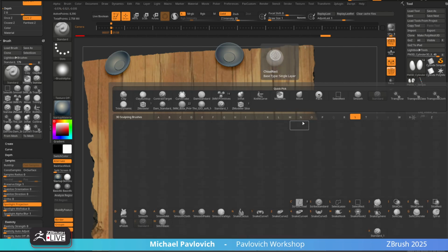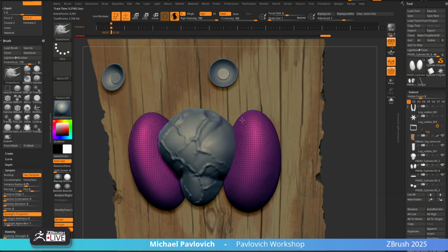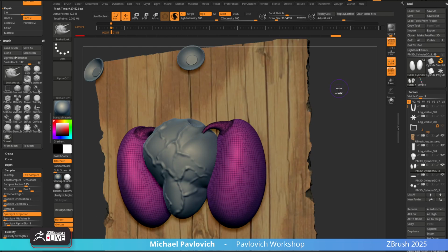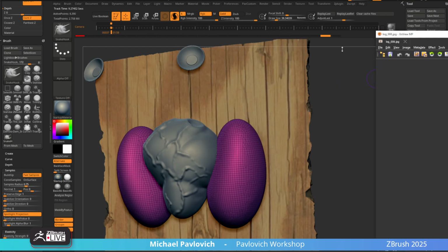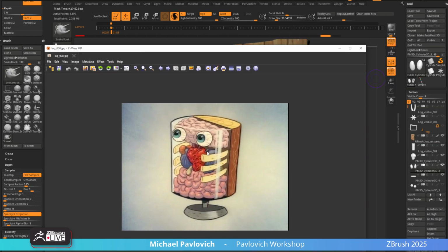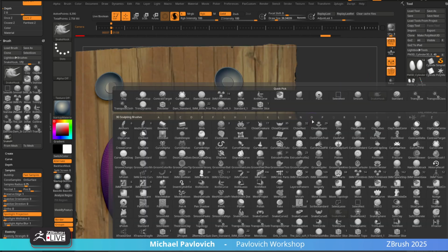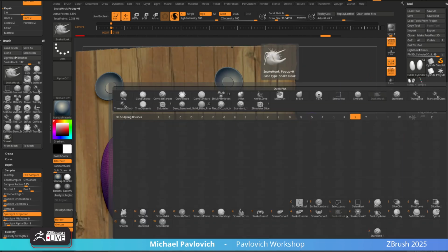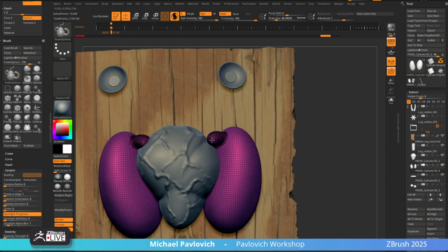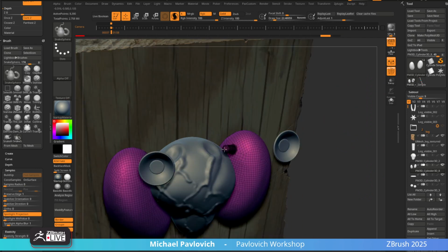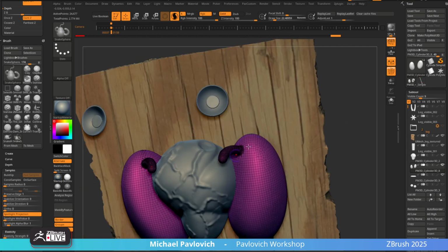And BSH for the snake hook brush, you can turn on Sculptors Pro. You can literally go in here and just pull tubes out of this thing. So that's what I'm talking about. When this, like this little stuff right here, you don't have to be fancy with IMM brushes or anything. And if you want a little fancier, you can go BS Snake Sphere. You can use this to kind of pull out a sphere here. Now you can see it's kind of coming at me a little bit.